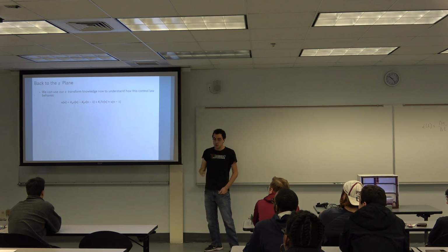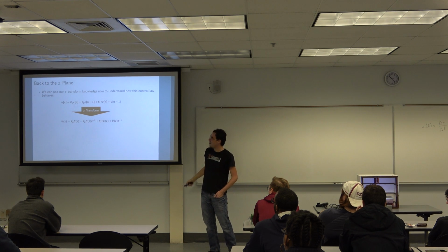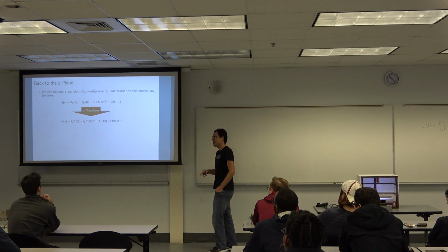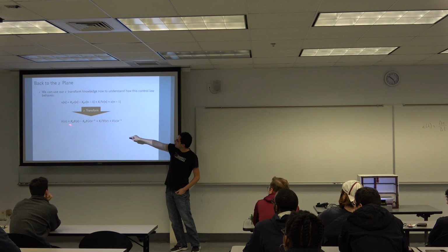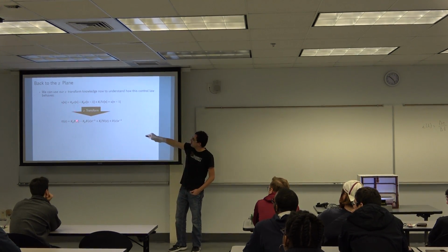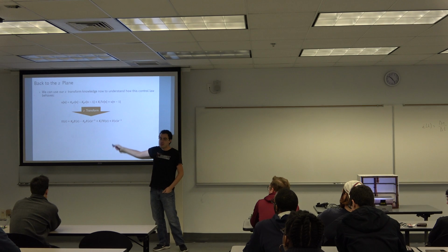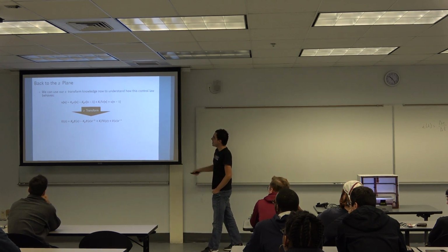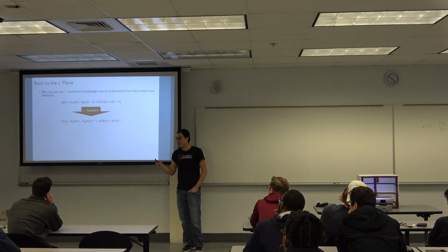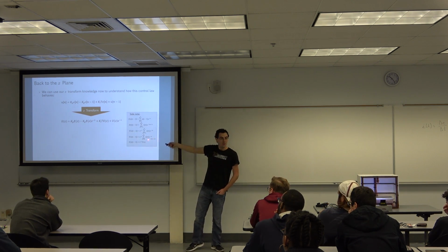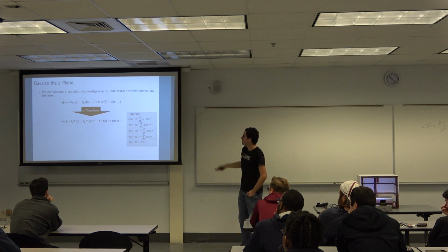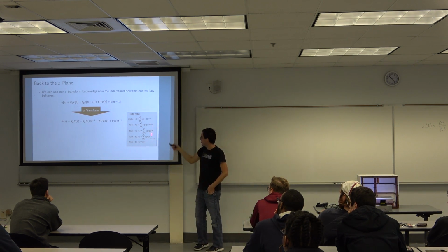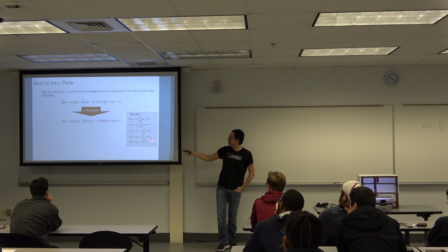This guy here is a little bit tricky, so I'm going to have to spare you the details. So U(z) comes from u(n), the constants just carry over. But e(n-1), I'm claiming here it's E(z) times z to the minus 1, or 1 over z if you will. And this minus 1 means the last sample. And this is the proof. I'm not going to go through the details, but you can stare. If you stare for long enough, you're going to be able to believe.